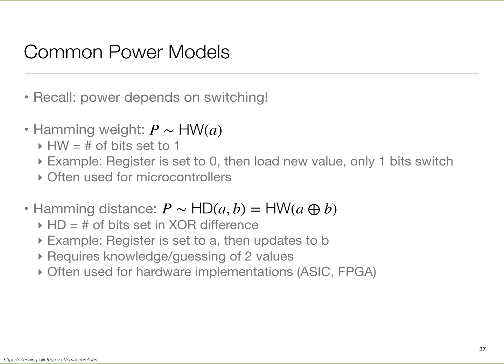You can do it at the circuit level. You can do some stuff at the voltage regulation control level, with the operating system, and you can have your application code, your algorithm, designed in a manner where it takes constant time. There has been lots of work in recent times on compilers, where I give it the code and it generates code that will be constant time. It's very hard to be truly constant time because you still have effects like caches, but you can try to achieve that.